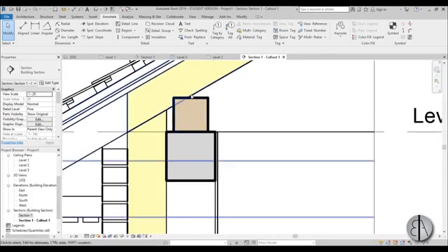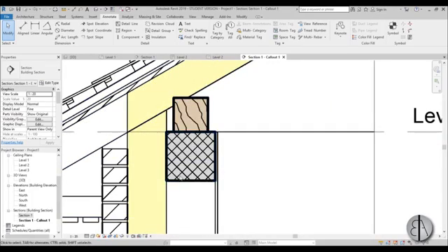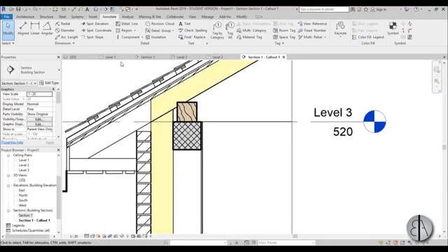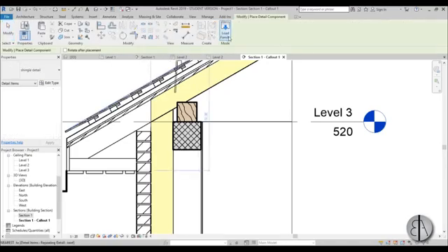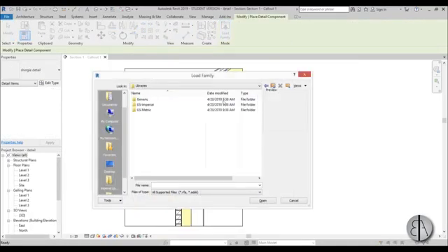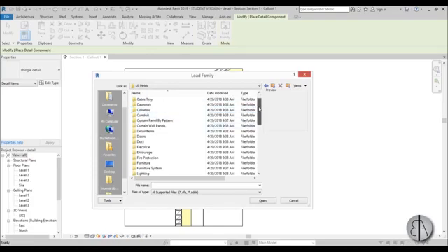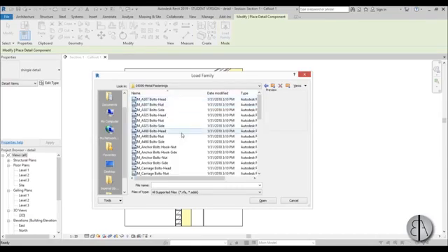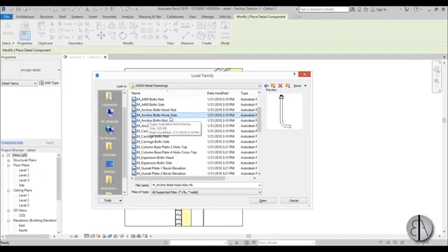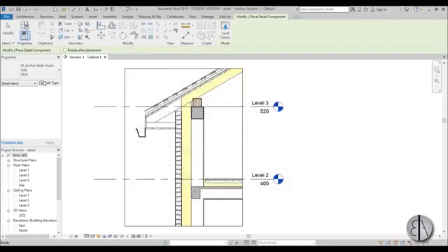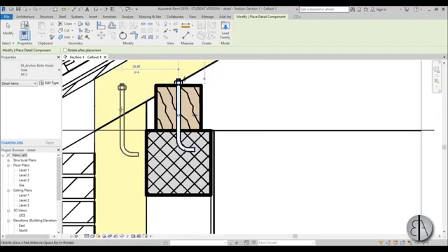where that connects this wooden beam to our concrete beam underneath, and I'm going to be loading that in as a component. So just go here, Detail Component, and you go Load Family, and I'm just going to go back one folder to the metric library. Here you have these detail items, and I'm going to go to Metal Fastenings, and then scroll down a bit. Okay, here you have Anchor, and you have this side view or the nut view. Sounds funny. Just open it up, and here I'm going to choose this M12 size and place it like so.